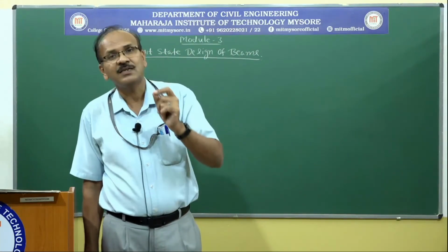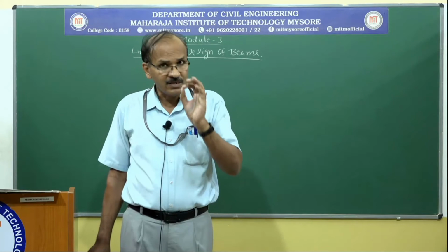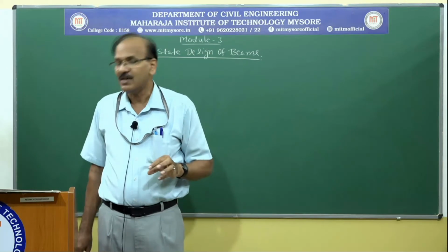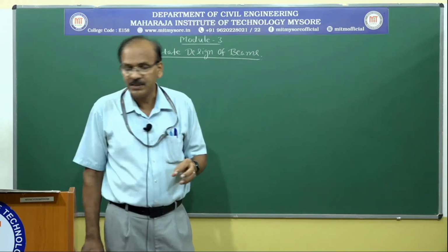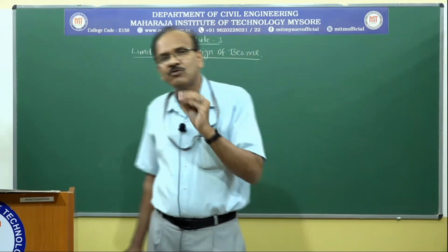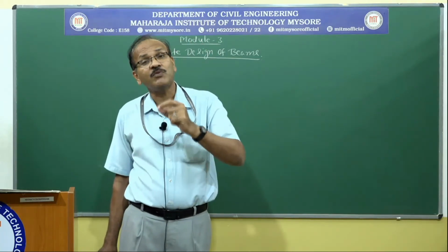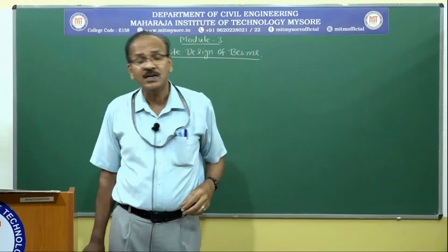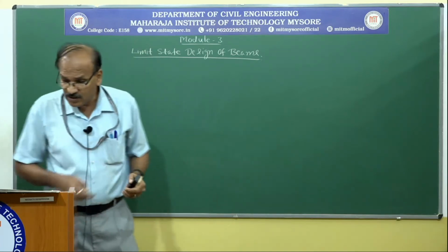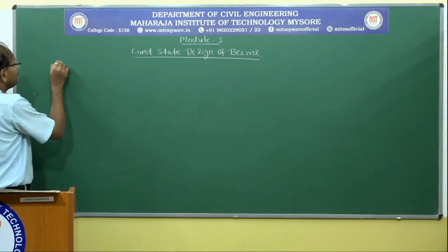In addition to that, we are going to check for the serviceability limit state, that is, the deflection. Here we are not going to calculate the actual deflection. Instead there is some codal recommendation, and once those recommendations are satisfied, then we do not have to check for deflection. That is what the code says, and that is what we discussed in the first module when we covered deflection and cracking in detail. So coming to the design, please write down: